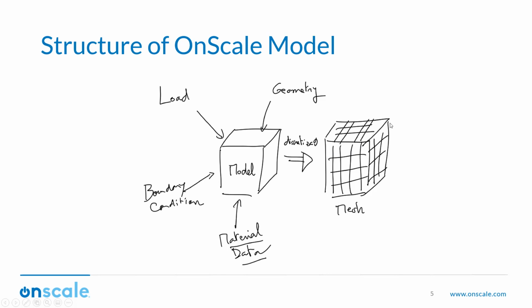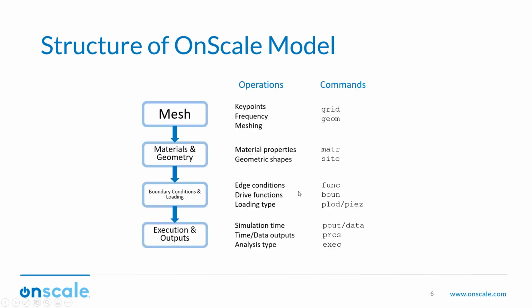The good point about that is that it's mainly automatic. No need to really refine the grid on some specific parts. Well, in some cases you need to, but it's not exactly working like in the other software. And generally, it's pretty automatic. We have also other kinds of meshes in OnScale, like Tetra Mesh, etc., which is also available in the analyst mode only for the moment. But the main type of mesh which is used now is the Hexa Grid Element.